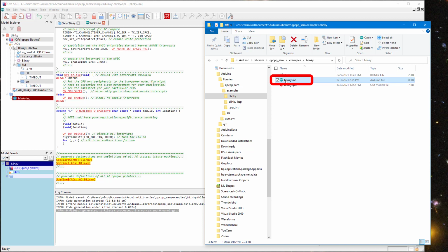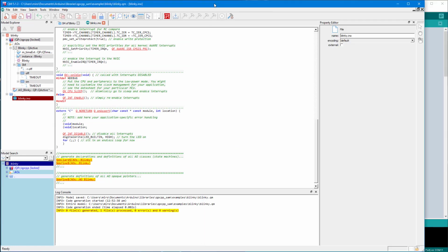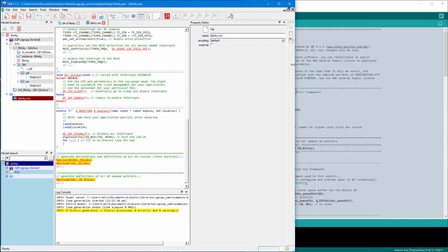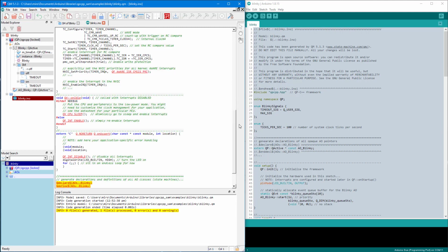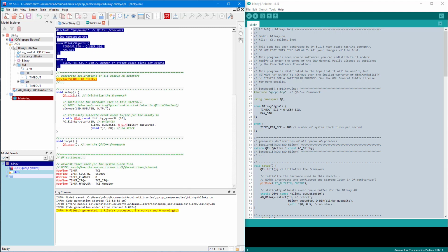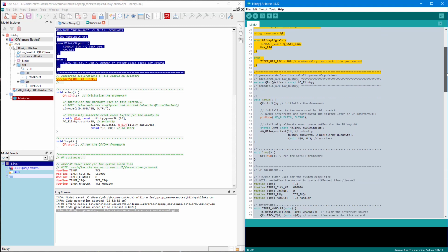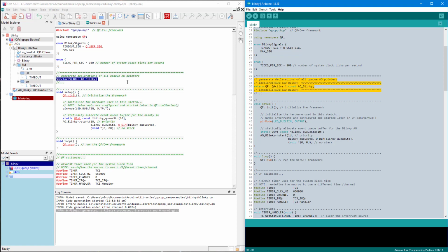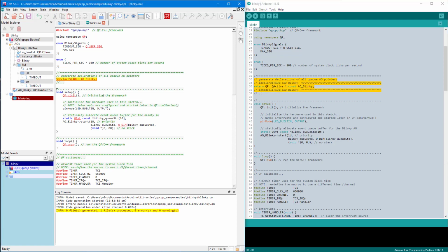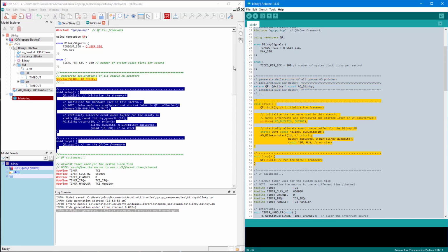This generates the complete blinky.ino file on disk, based on the blinky.ino file template in your model. The file is always regenerated, but it is replaced on disk only when there are differences. Now, when you compare the file template in QM and the generated file on disk, you can see that the file on disk has all your code literally copied over, but all $declare and $define directives are now replaced with the generated code. This makes it very easy to mix handwritten code with auto-generated code.